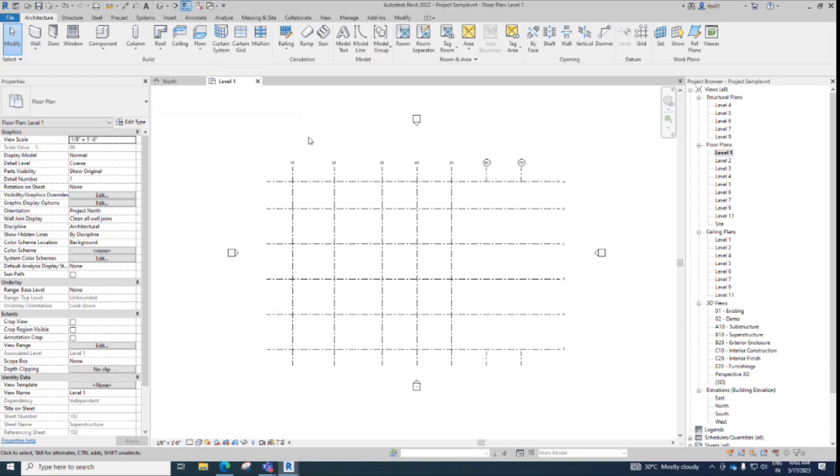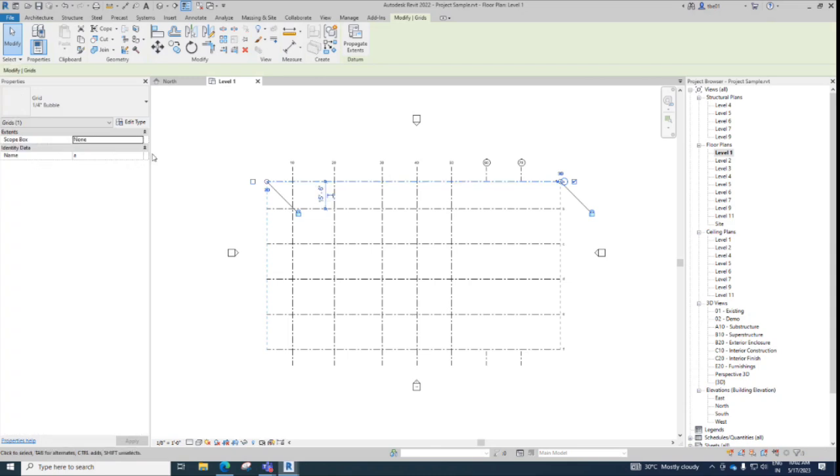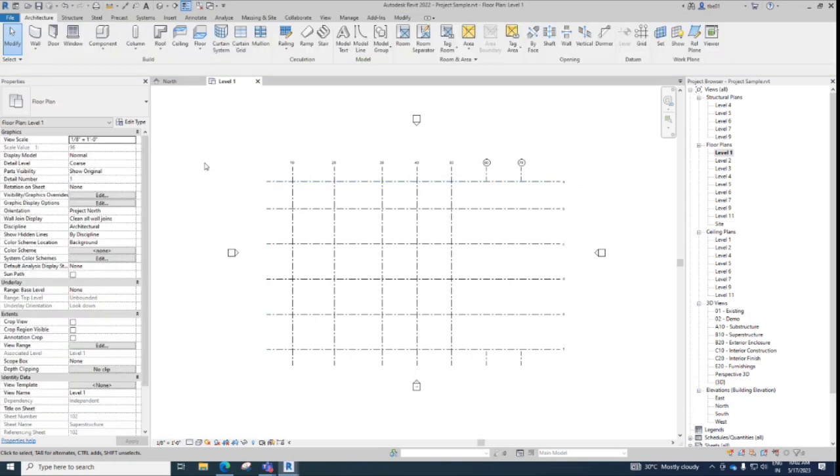This is very important because you should understand, if you make a change in the instance properties versus making the change in type properties, what effect it is going to have on the overall model. So make sure that if you want to change something very exclusive to one instance, it should be controlled by an instance property and not a type property.